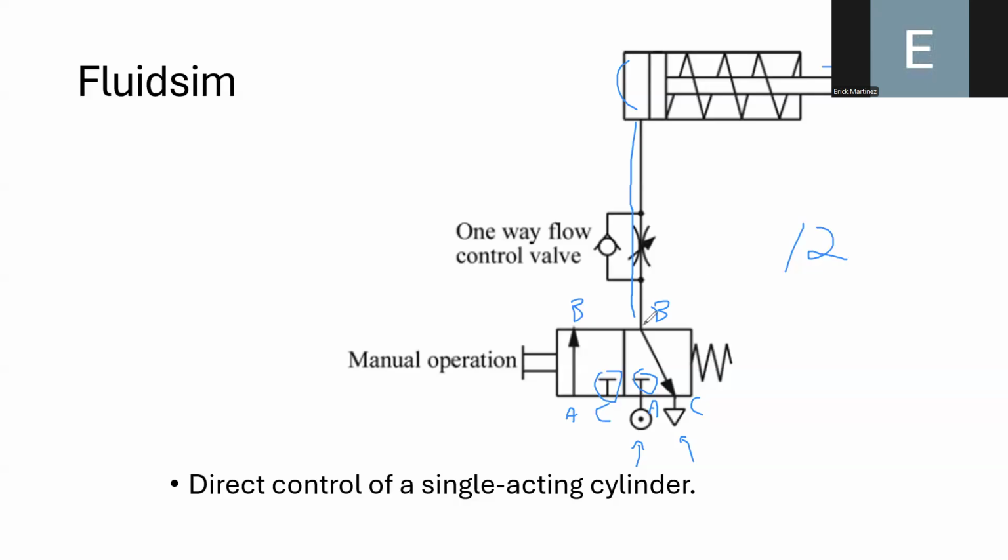So just to finish this part, just remember that this directional control valve has 3 ports. So we can denote that by these two numbers. The 3 refers to the number of ports. We have a diagonal and then we place a 2 that basically refers to the number of positions. Okay. So that will be all from my part for this video.